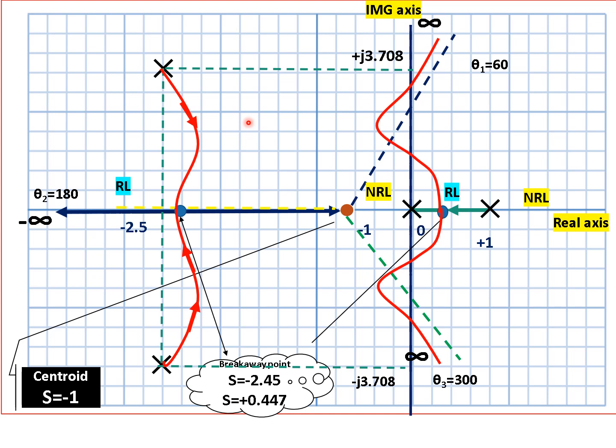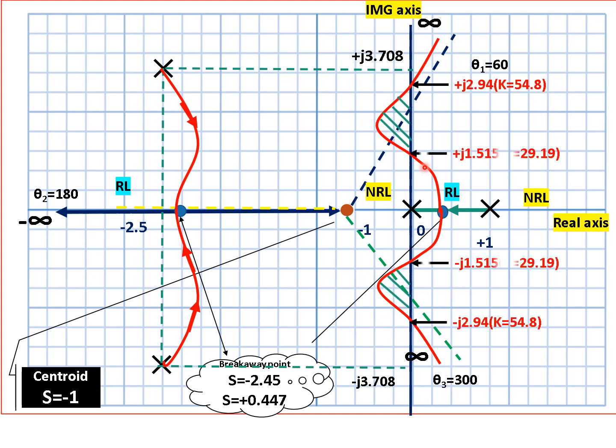Next we'll draw one more curve, and we have calculated two marginally stable conditions. Let us assume that since there are two poles and a breakaway point, the curves will start like this in opposite directions. Now let us consider only the upper part of it, and the lower part will simply be a symmetry, or a replica, of the upper part. So let us assume that this line is moving like this.